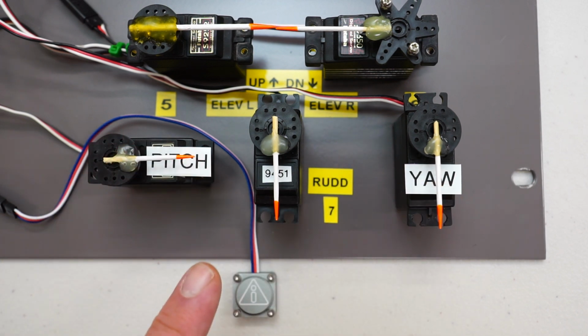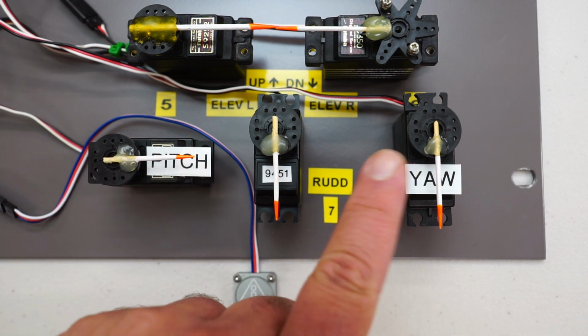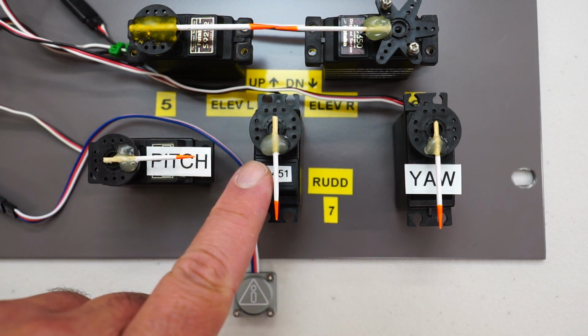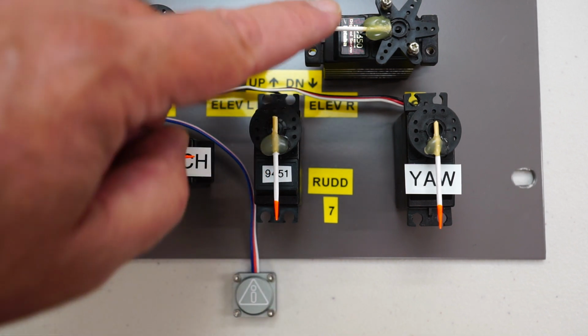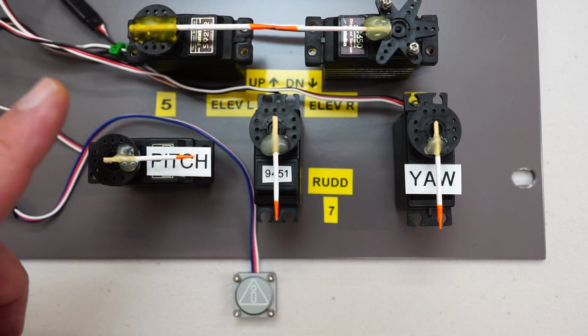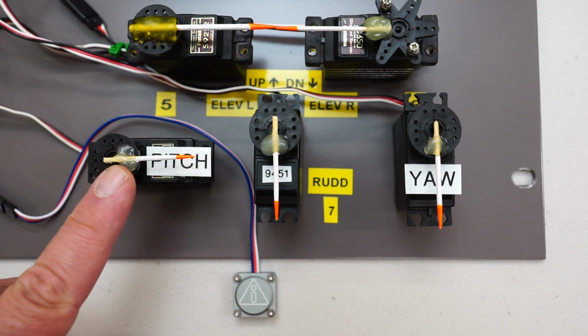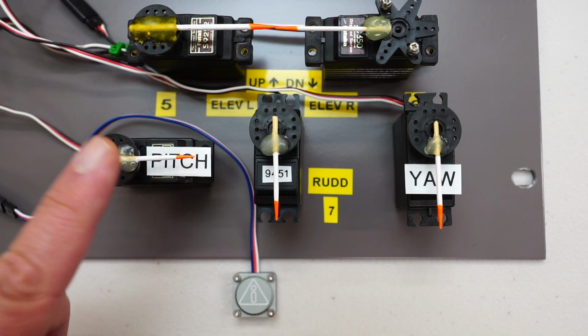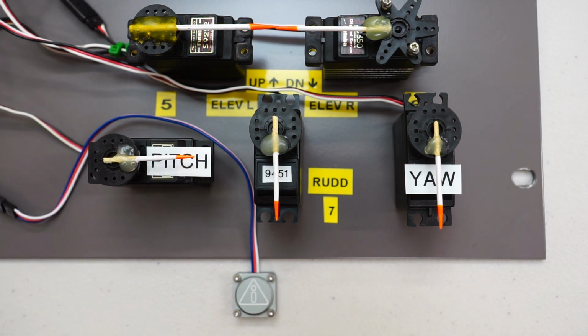So we also need to switch the gyro off just for these two guys. We still want the gyro working on our rudder and our two elevators, as well as our ailerons. However, we don't want the gyro to be operational when we switch off the vectored thrust nozzle steering, if you like. Okay, let's switch over to my core screen and I'll show you how to set it up in a few easy steps.